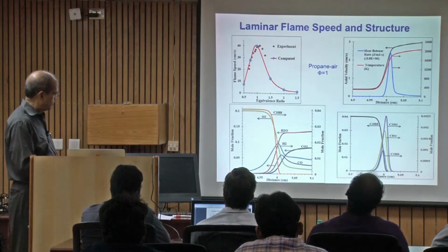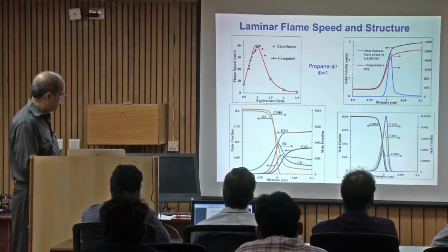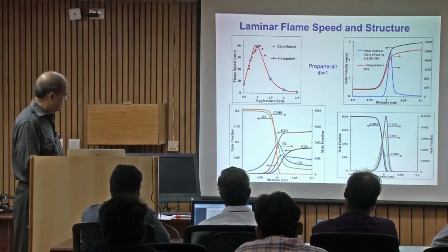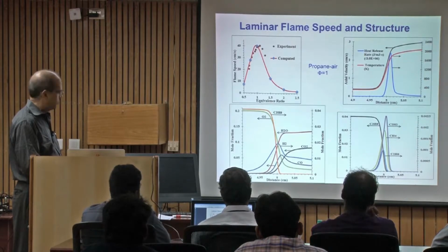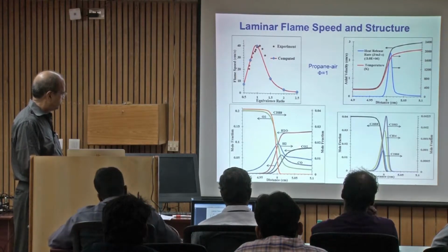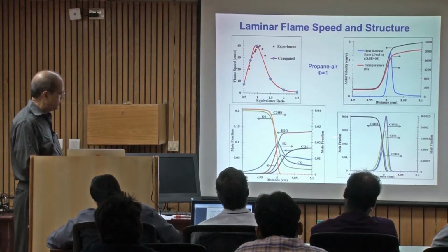Oxygen, propane, okay, and then H2O, CO2. Again, you can see the H2O starts forming earlier compared to CO2. And then H2. So when you analyze these premixed flames or even diffusion flames, these are the major species you plot.